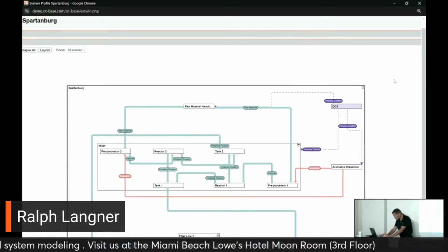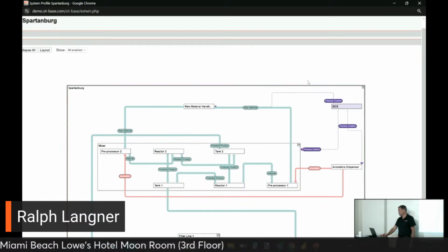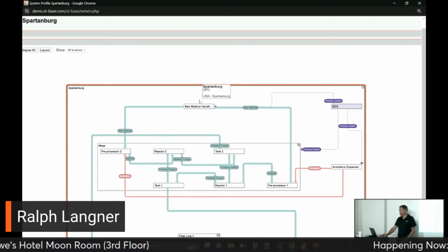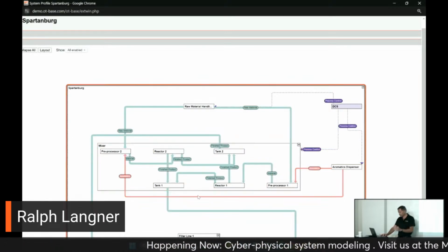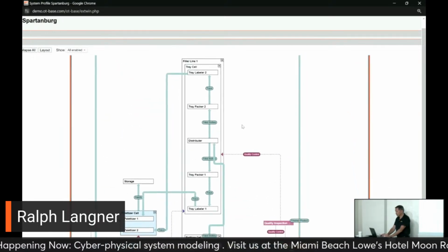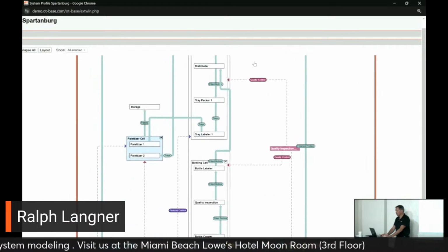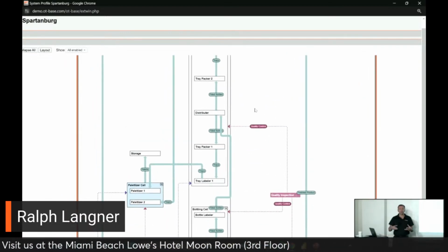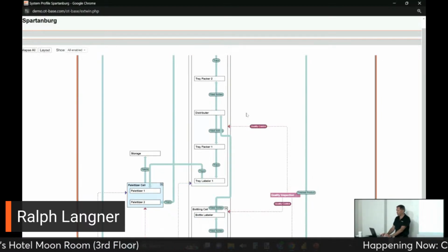Then you see the various dependencies. Here we got a DCS that exercises process control for the raw material handling and also for that mixer. And that mixer is redundant. And from that mixer, when you go further down, we also have a filler line where the product is bottled and packed into trays and finally put on pallets, right?